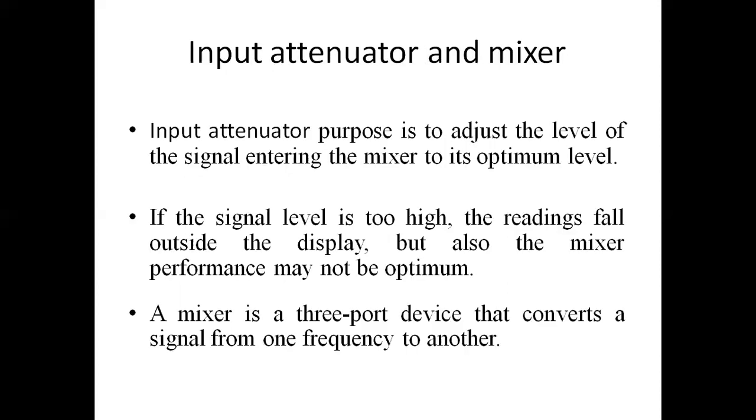The first component is the input attenuator and mixer. The purpose of the input attenuator is to adjust the level of the signal that is entering the mixer. The mixer has an upper limit for accepting the input signal. So the basic characteristic of the attenuator is to attenuate the input signal to the optimum level that is acceptable by the mixer.